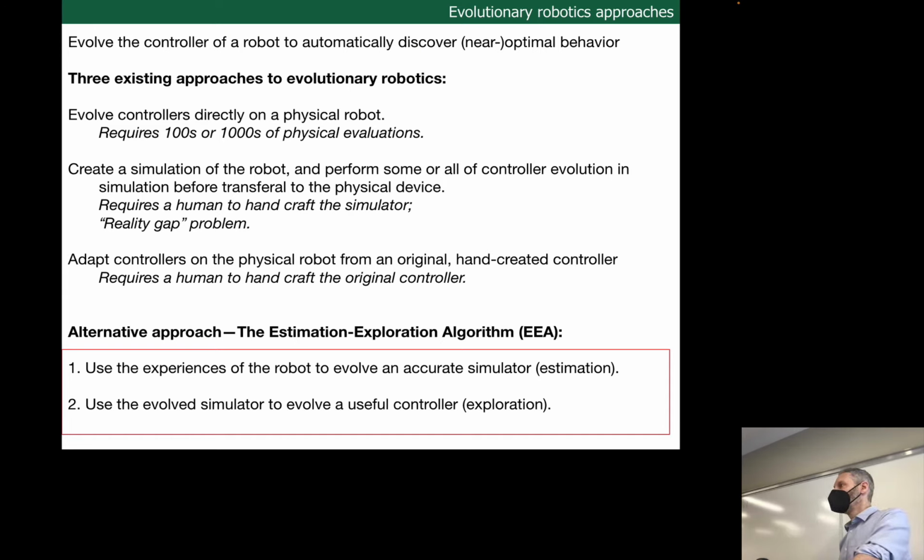Nice generalized surface friction or something. Okay, so friction is usually at the top of the list. This is super hard to get right. We've actually hidden the details of how you specify friction and surface features in PyBullet. You can take all of those parameters and all those features, and we can add them to our genome. We can evolve the friction parameters of the simulator. What else?